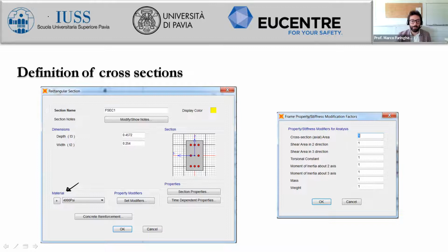But we have to keep in mind that SAP 2000 allows for the most general formulation, so according to the Timoshenko theory, the effective stiffness and deformation for shear forces. This is the reason why generally when we try to compare hand computations with what is returned by the software, maybe there is some mismatch, because hand computations are generally related to the Bernoulli formulation for beams, which neglects the deformation with respect to shear.